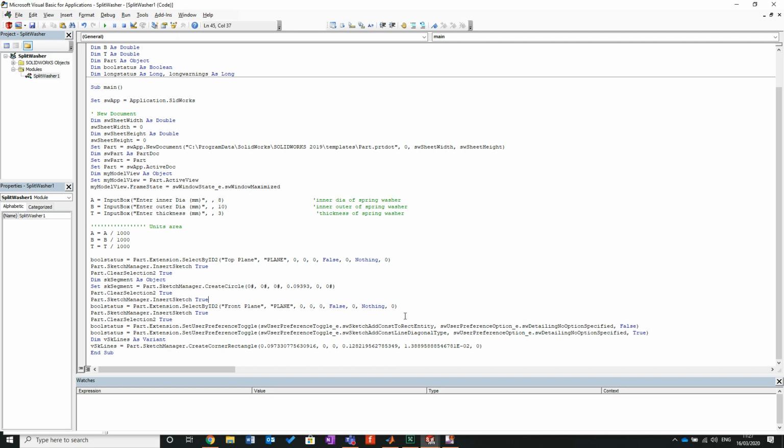Let's make it the inner diameter. So if we make it the inner diameter, I'm going to set that to A. Now I've asked for diameter, so before I make the obvious mistake, I'm just going to divide that by 2. Now what it'll do is it'll come in and it'll set that in it. So again, I might forget what I was doing, because I do.